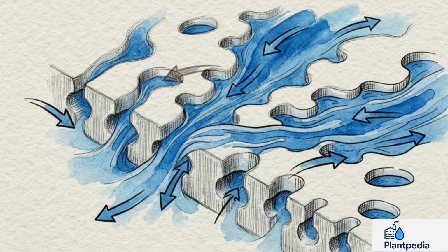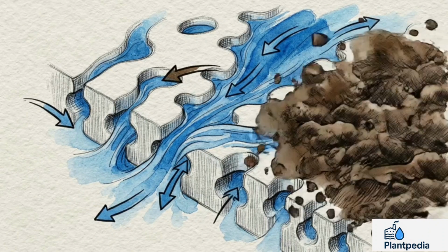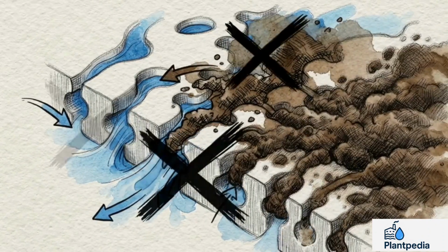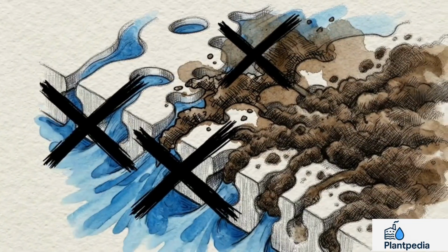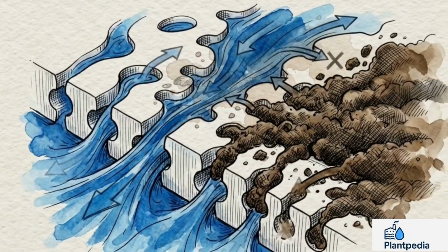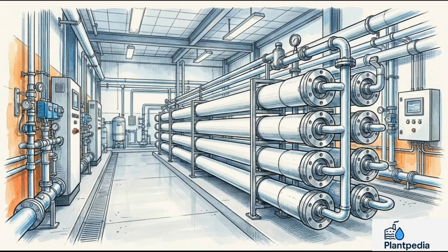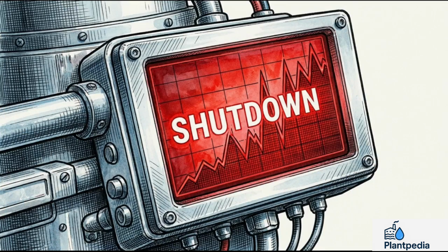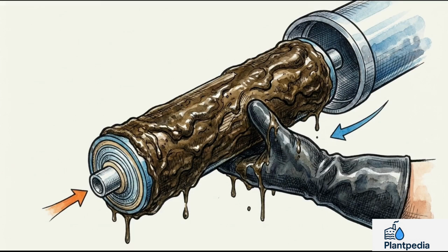This shows what happens when untreated water hits a pristine microporous membrane. Watch how dark particulate matter immediately chokes and seals those tiny pores. Industrial reverse osmosis, or RO, membranes are extremely sensitive. Even microscopic suspended solids and slight variations in turbidity will completely shut them down.